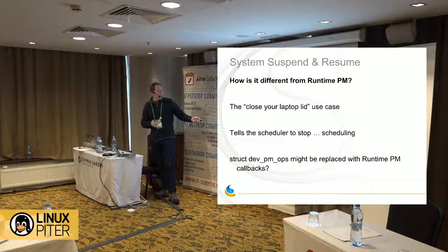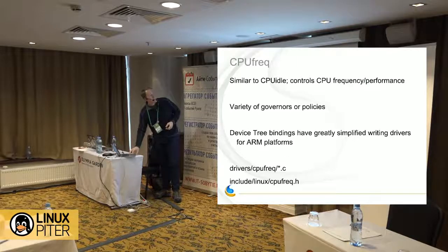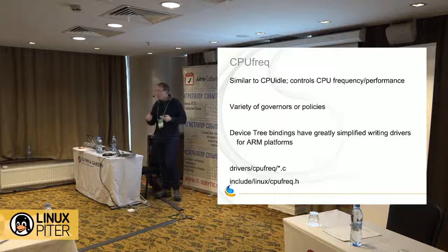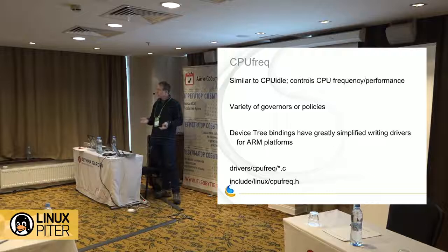You can look at the struct dev_pm_ops to see how it's used. These are the suspend and resume callbacks that many of you will be familiar with inside of a device driver. Similar to the CPU idle and runtime PM migration, this stuff might merge as well with runtime PM, and that's been an ongoing discussion for some years. Where if you already have code that can put your chip into a low power idle state with runtime PM, can't you just reuse that to implement suspend and resume? And for many platforms, the answer is yes. So we're starting to see a migration where these two subsystems are merging.